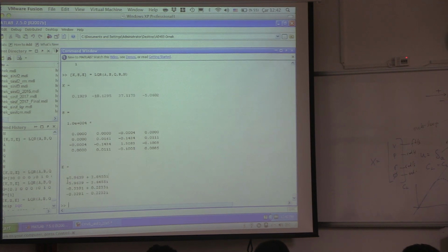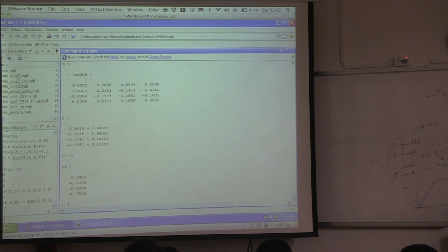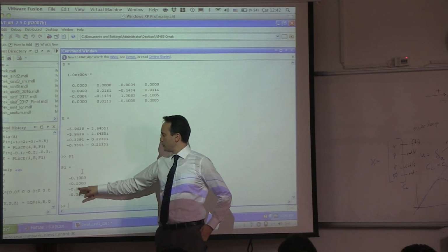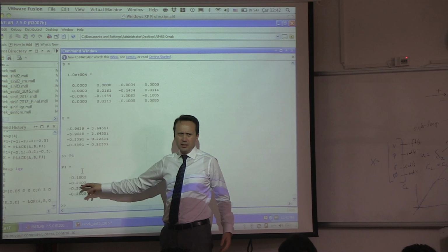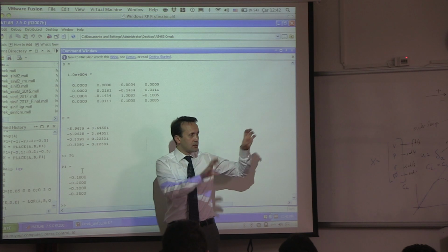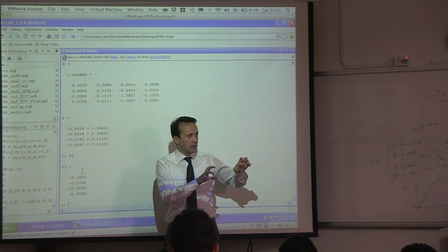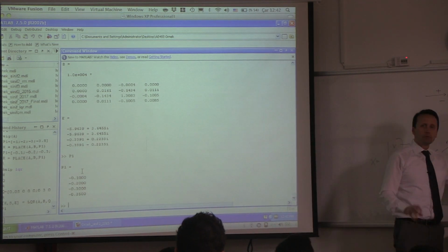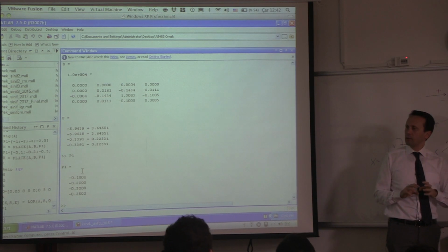Okay, 2 of them are now complex. 2 of them went to -5, -6, and 2 of them went to -0.3. So remember when I did the place matrix, I made up the eigenvalues where I want to move them. I moved them to -0.1, 0.2, 0.3, 0.35, but I really didn't have an understanding of which states I want to put more emphasis on, right? I just said move the eigenvalues over there. But which states should move less? There was no understanding of that.